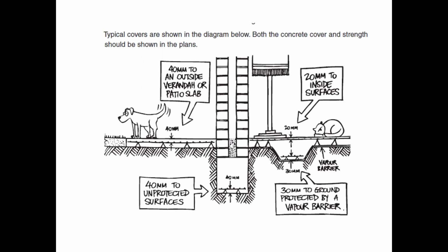so the reinforcing steel is a lot closer to the surface. That's to help reduce cracking, because we wanted a nice looking concrete surface. And also it's not outside in the rain and everything else, so it doesn't need as much cover. So there's a couple of reasons why they've done that there. And don't forget, on the inside there, we've got our plastic sheet down to stop any water or vapor coming up through. So you get a lot more control inside than you do outside. So it's just a good example, especially for those that are new to concrete.